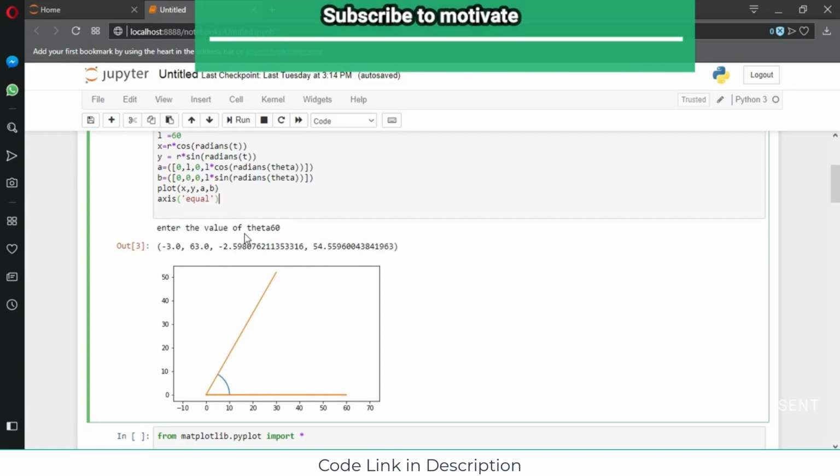Now let's try to understand these two lines. Here a 0 comma 0, so the line starting point is 0 comma 0, and the second point is L comma 0. So the line goes to the L comma 0. After that, the line again goes back to 0 comma 0, and after that, this point is defined by L cos radians theta, L sin radians theta, so that we get this point.